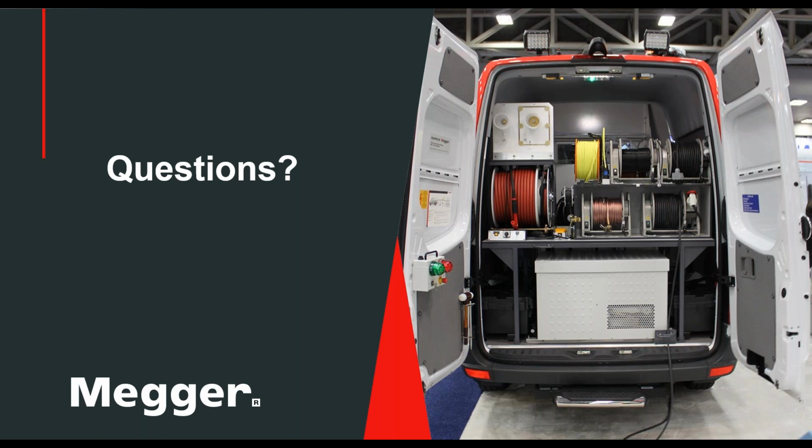So from a practical point of view, as long as you keep your voltage under control and you're not excessive in the amount of time, you're not out there thumping on a cable for half a day because you're not using the right technique, you're not really too concerned about damaging the cable itself with the thumper. I think that's a very important comment you made, Marshall, to use the right technique.